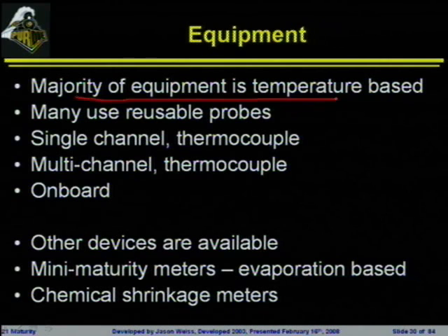Many of these are reusable probes. As I mentioned in the lab, we use a simple thermocouple wire that, while the probe itself is technically not reusable unless you break it out of the concrete, you could snip it off with wire cutters, get a soldering iron out, and you've got the exact same probe, only it's 4 inches shorter than it was last time. So there are a lot of probes that are like that.